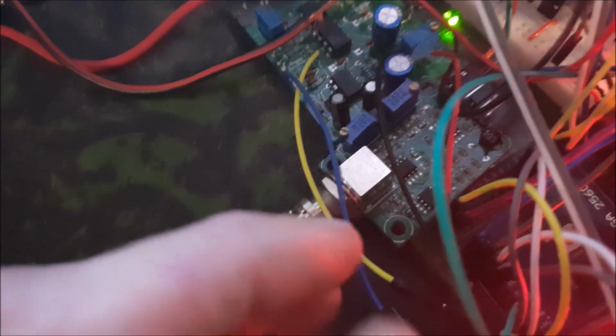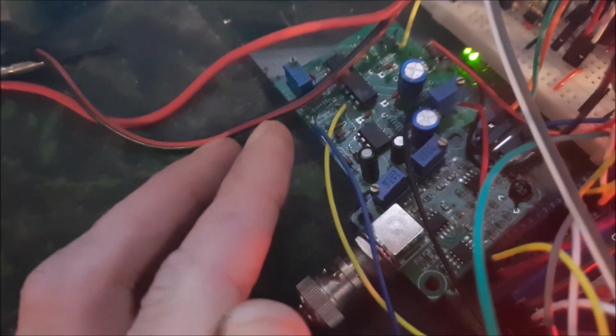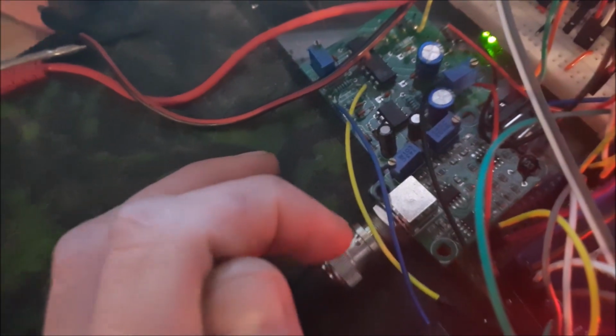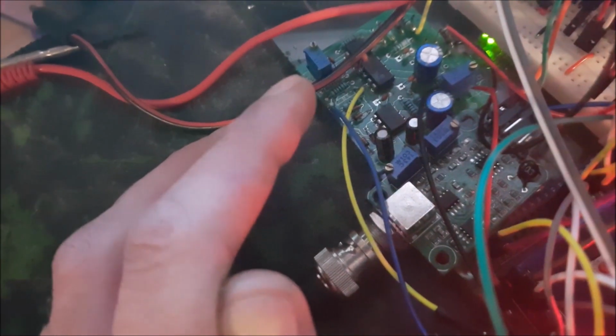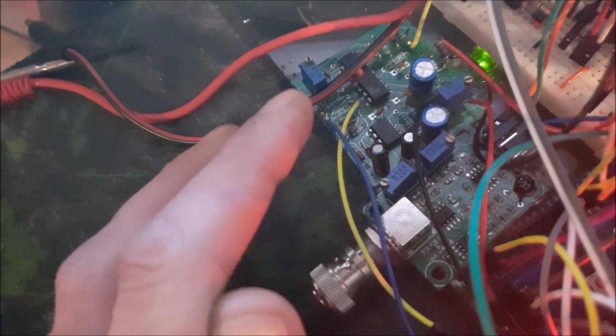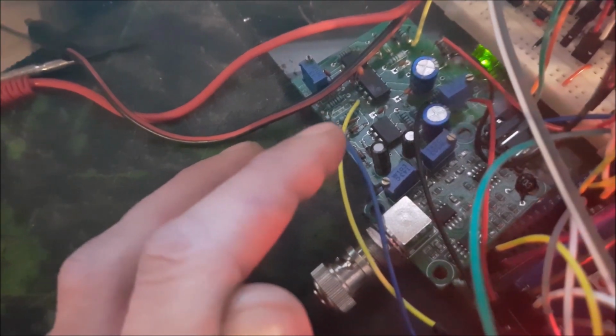What's happening is, both of these work on conductivity. There is a voltage being sent down there, and it's working out the resistance, or the conductivity, respectively. The EC sensor is conductivity, this is resistance. Or that's how these sensors work essentially anyway. If I have an earth from this connected whilst this is reading, some of that voltage is going to go down this earth, and this value is going to be off. If I have the power cable from this active whilst this is taking a reading, it's going to get a different reading as well, because it's going to get some of this voltage induced.